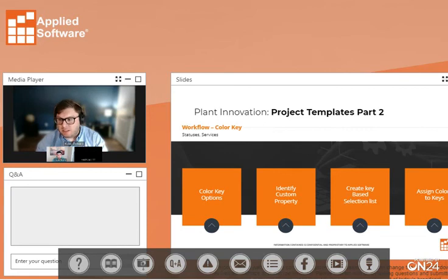That's really the most common one, statuses. Being able to quickly identify these in things like model reviews is extremely important. So being able to go in and set those color keys to your preferences, and then assign the color keys using things like the P&ID Painter. Extremely useful.